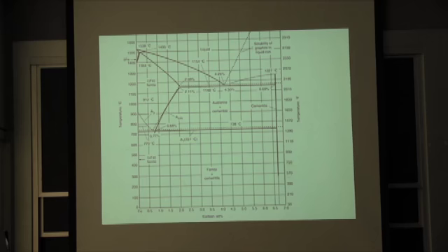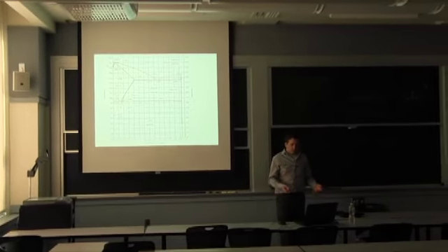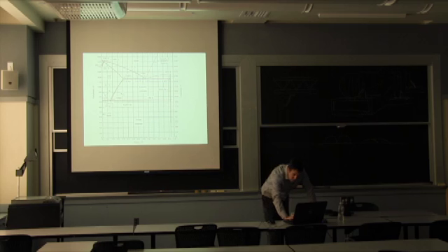The idea here is to show phase stability. That's what a phase diagram is for. It's built out of thermodynamics. So what is the stability of a certain phase at a certain temperature is what we're looking at. And there's a lot of information, and I'm going to walk through it with you. If we take the column for iron, so we say there's no carbon, well, the diagram shows this is the liquid phase, up to 1538 degrees centigrade right here.